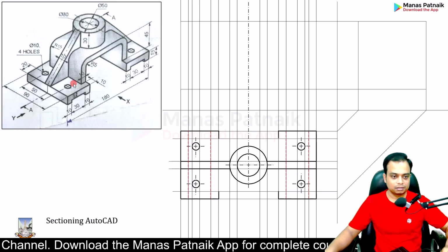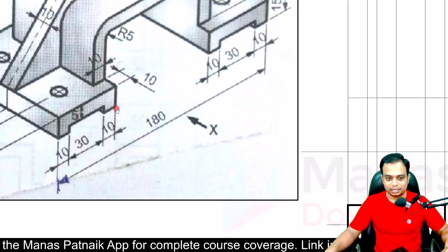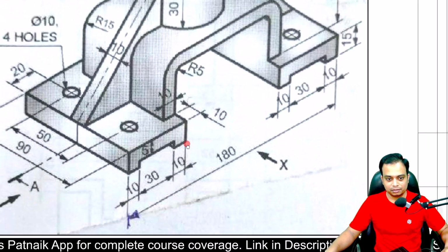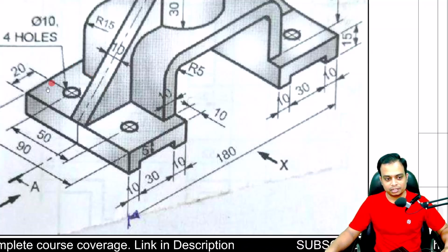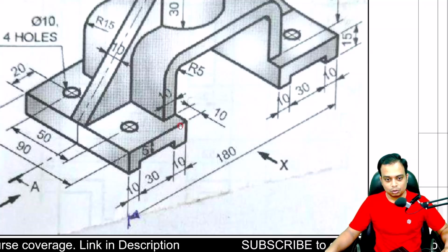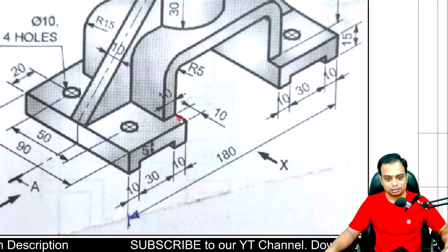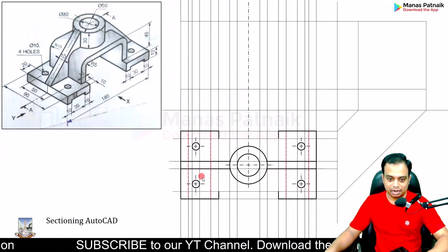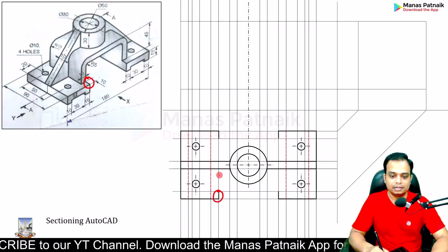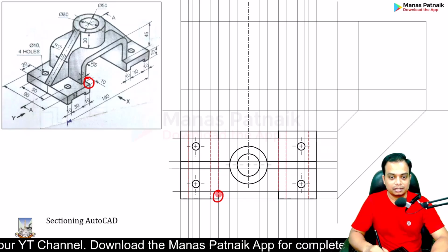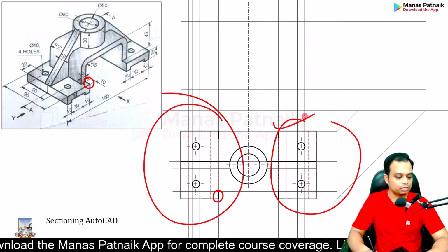And then if you watch, students, there is a solid edge over here. Right below this edge, there is one more edge which extends in this direction until you travel a distance of 90 millimeters. So some portion of this edge is falling just below this solid edge. So leaving that portion, I'm talking about this portion, the remaining portion is hidden. That means you have to use a dashed line like this. Done. The same stuff over to the right hand side. Whatever has been done to the left has to be done to the right hand side.